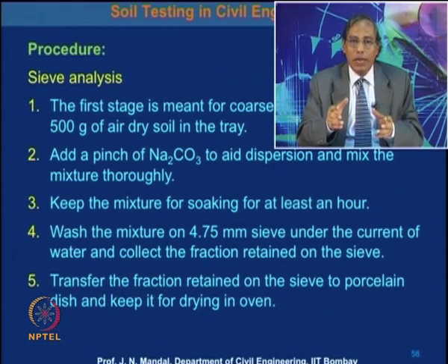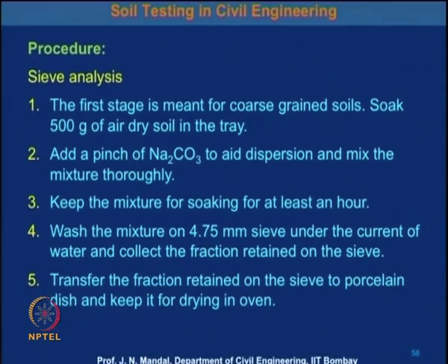Wash the mixture on the 4.75 millimeter sieve under the current of water and collect the fraction retained on the sieve. Now, transfer the fraction retained on the sieve to a porcelain dish and keep it for drying in the oven.